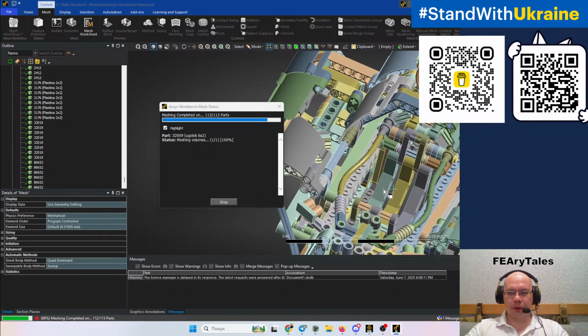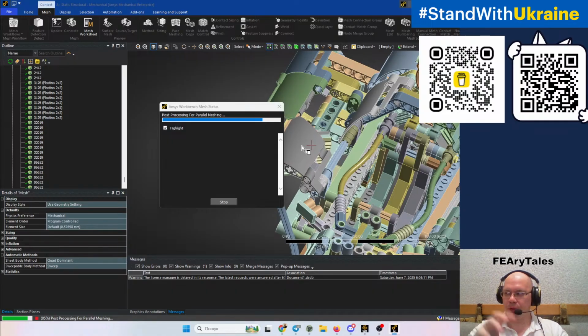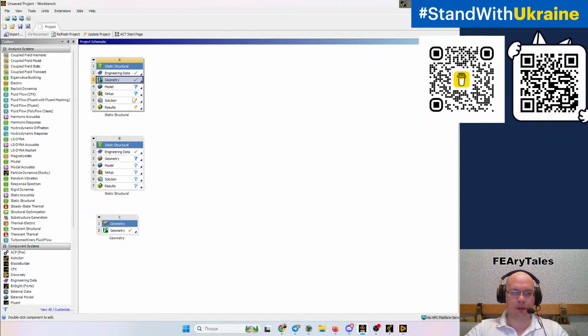If you have the original CAD data, then maybe it's more helpful to not import the full assembly as one file, but import some sub-assemblies as separate objects here, and then create the mesh assembly inside of Ansys. It also can be done.